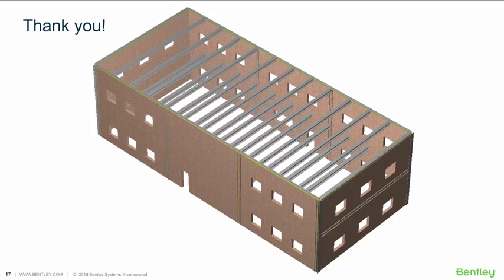Can you use RAM shear wall designer for masonry? You know, we have the concrete wall design module on RAM structural system. Short answer, no. You might think that maybe you could use it for a solid grouted wall, but bear in mind that the shear wall designer in RAM implements ACI 318. So the phi factors, the minimum steel requirements, all that is purely ACI 318, which is really why we need to bring in RAM elements into this workflow here.